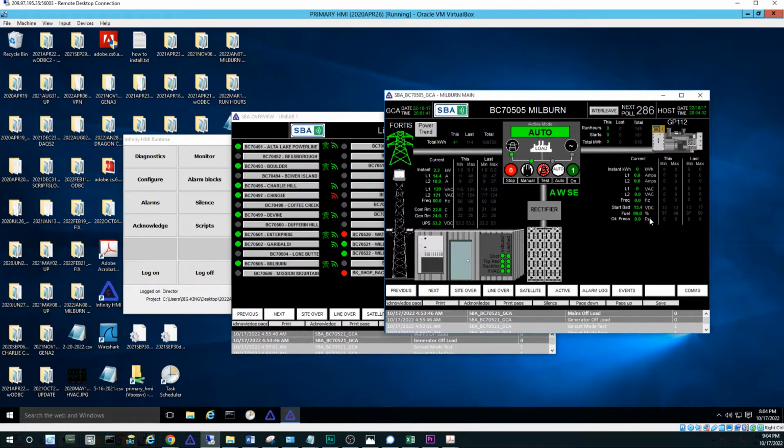These are good indicators of overall generator health, and provide good information for technicians in the event troubleshooting is required. These are also good to review on a regular basis when planning maintenance to get in front of weak generator start batteries or engines encountering low oil pressure. Being able to see today's extreme values and yesterday's is helpful in determining how service issues are developing, assessing fuel reserves during emergency operation, and verifying that previous days' repairs have been successful. Under the utility power side of the screen, these values are mirrored for the utility line.